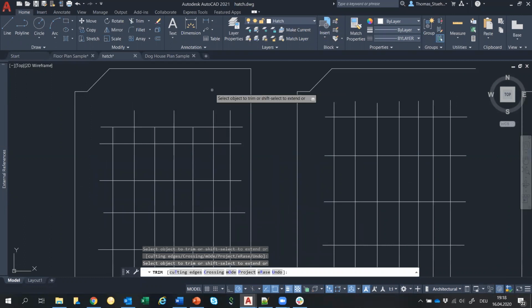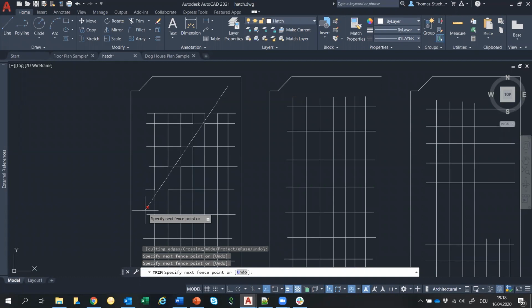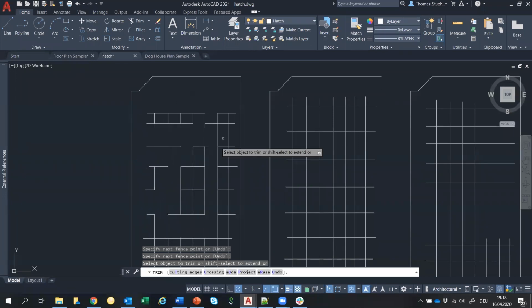And we have enhanced functionality too. We can, next to this single click, use a two-click fence. That means everything that is cut by this fence is trimmed. We can see here really comfortably what that means for my grid. Everything in between is trimmed. Next to this two-click fence, we can also work with a lasso. Freehand, just browse through my grid and everything that got hit by the line is directly cut. Very easy, of course.